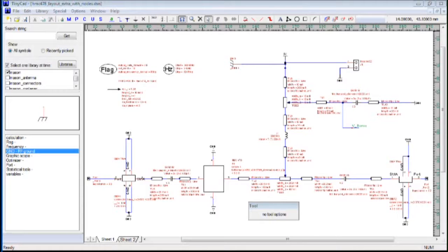A couple other things to point out. In general, we map these microstrip lines to somewhere around the center of where they get de-embedded. The terminals are electrically trying to model the length of the microstrip line, and it's not really accurate to map these de-embedded things right to the edge of the physical pad.